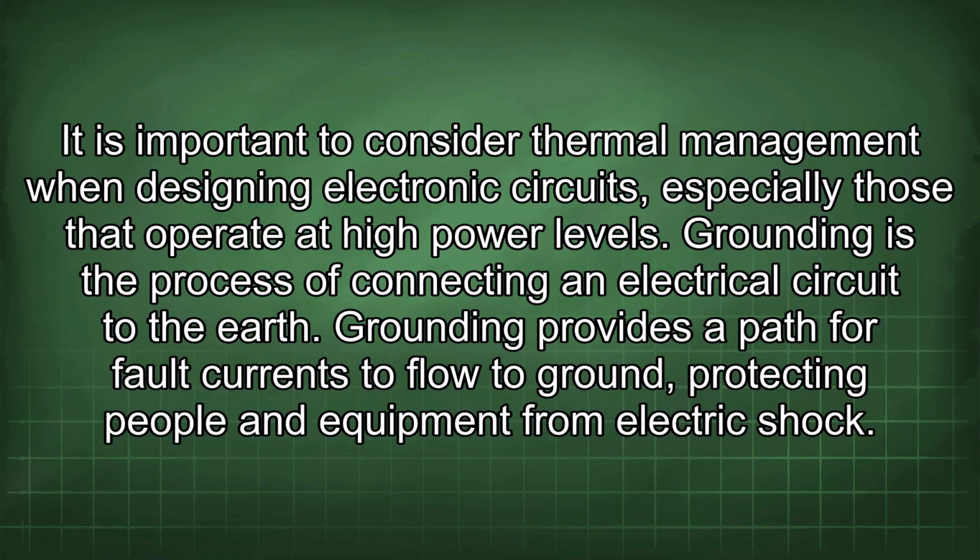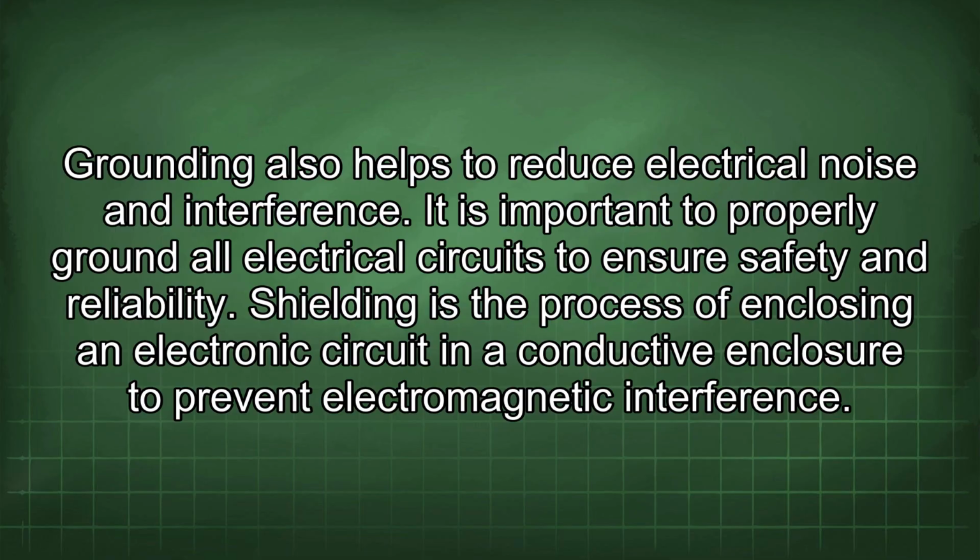Grounding is the process of connecting an electrical circuit to the earth. Grounding provides a path for fault currents to flow to ground, protecting people and equipment from electric shock. Grounding also helps to reduce electrical noise and interference. It is important to properly ground all electrical circuits to ensure safety and reliability.